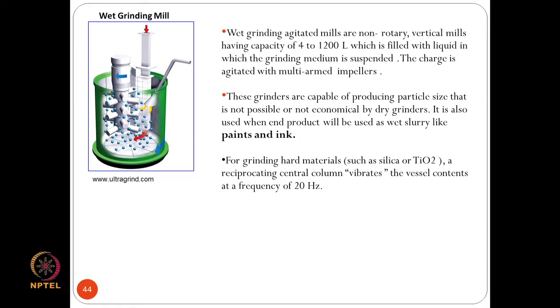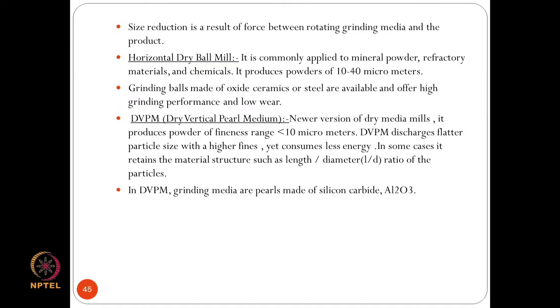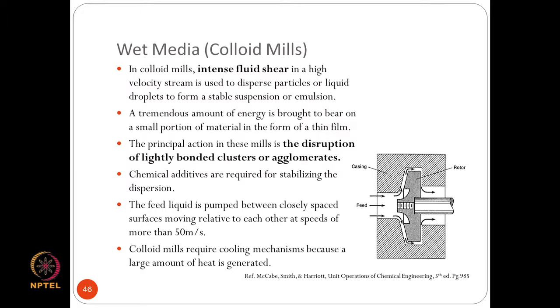Wet grinding, again, as I mentioned earlier, is a good alternative to dry grinding, and again we do this a lot in our kitchens, where wet grinders are very commonly used. It has certain advantages and certain disadvantages over dry grinding. When you use a wet grinder for making very fine particles, you use a high velocity fluid stream, which introduces a shearing force to break apart agglomerates. And so, you can combine a wet grinder with a high shear module to produce extremely fine particles even in the submicron size range.